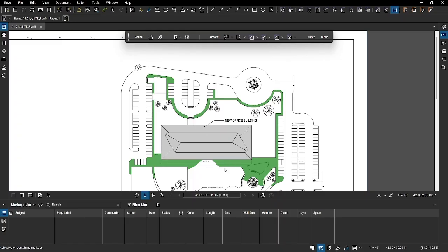If you look below the building, you'll see that the fill has gone far on the walkway area. In addition to creating boundaries for your fill, the Boundary tool can also create boundaries after you fill. Select the Boundary tool and create a boundary at the end of the walkway on the right side. The overflow will disappear.